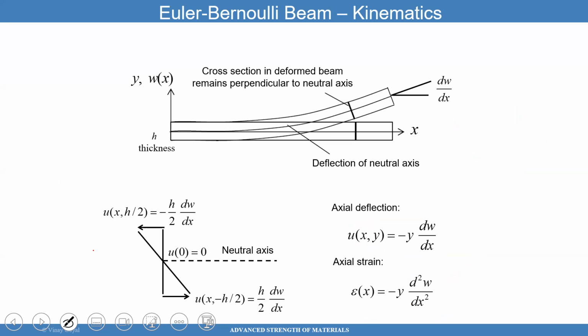Does that make sense? So in other words, if I have a beam that looks like this after I deform it, is that a lot of curvature? If I have a beam that starts straight and then looks like the one here, very smiley, is that a lot of curvature? Yeah, so then you have a lot of strain. That's what that's telling me, right? The more curvature, the more strain.